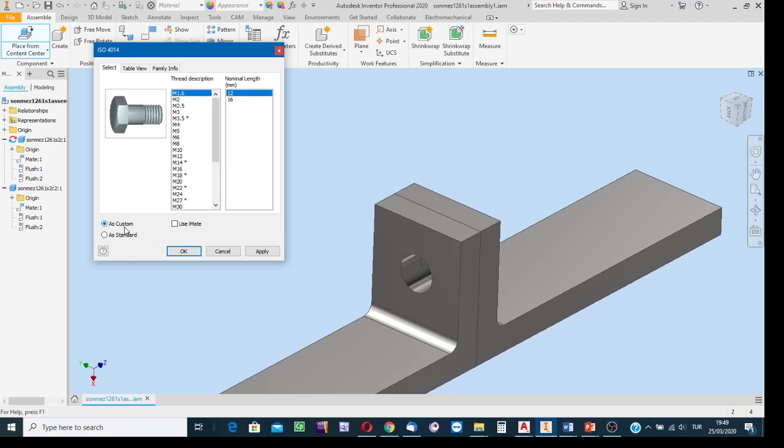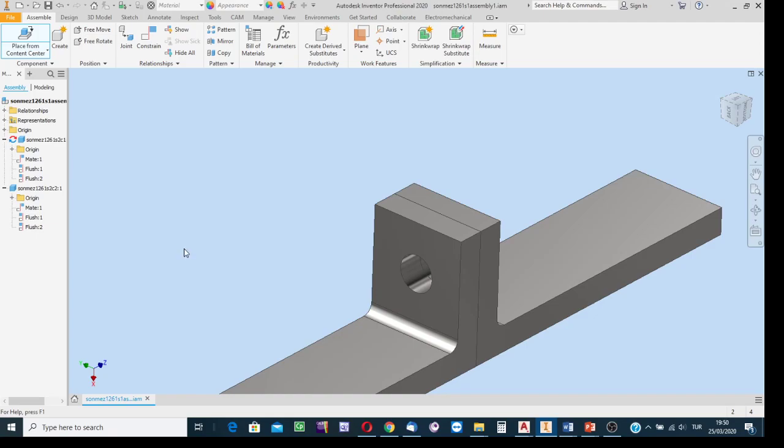So have it as a copy in the project folder. If you select the custom option, then the copy of the file in which Inventor creates and keeps the model of the component will be created in the project folder. Okay, diameter of the bolt is 10, and if I am not wrong, my calculation is correct, then 45 millimeters is the necessary length for the stem. Select this one and then say OK.